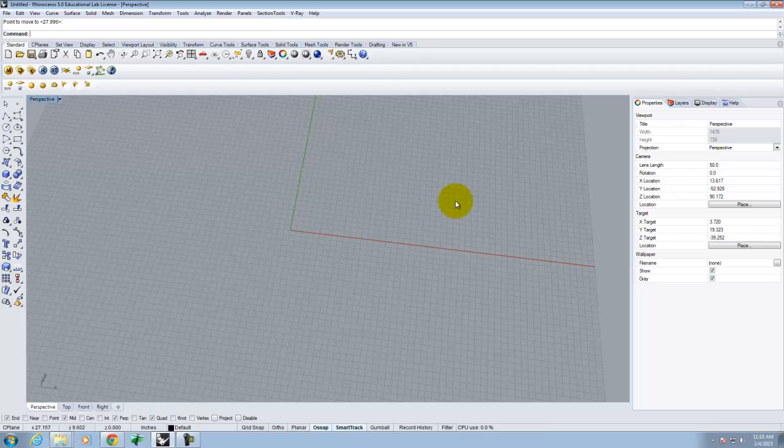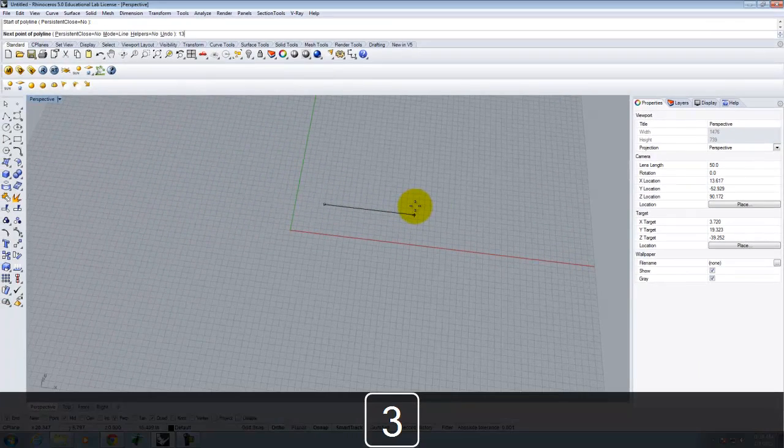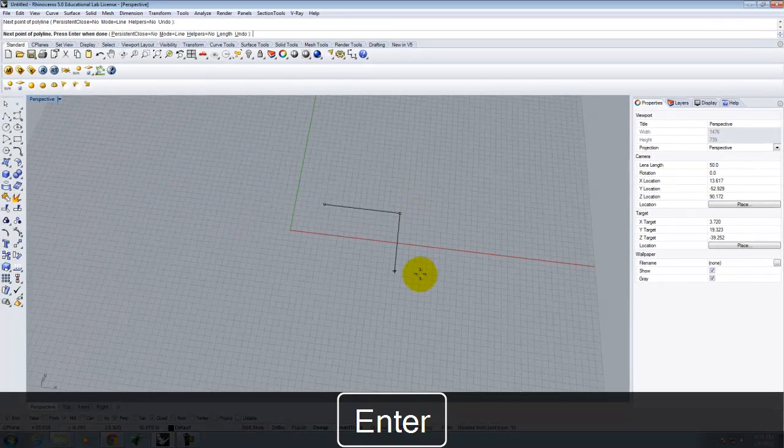So as normal, I'm going to go ahead and demonstrate what we'll be doing, and then you guys will be free to work through it and see how it goes. Okay, so I'm going to work with the Polyline tool to start. And I'm just going to pick, and I think I was very specific about where I started, but I don't really mind where I start for right now. I am going to make sure that I turn on ortho so that that's running. I do have my object snaps available should I need them. And I'm just going to go ahead and start here with the top line, which is 13 inches. And so I'll type 13 inches in that direction, and I'll hit enter.